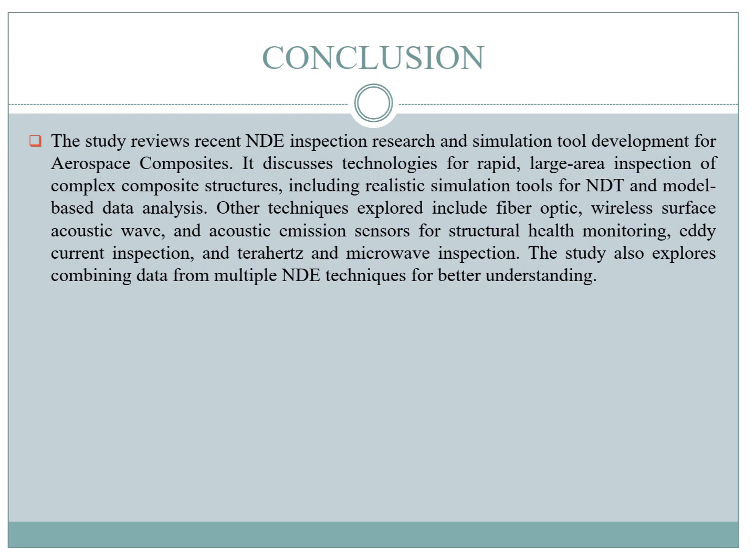and model-based data analysis. Other techniques explored include fiber optic, wireless surface acoustic wave, and acoustic emission sensors for structural health monitoring, eddy current inspection, and terahertz and microwave inspection. The study also explores combining data from multiple non-destructive evaluation techniques for better understanding.